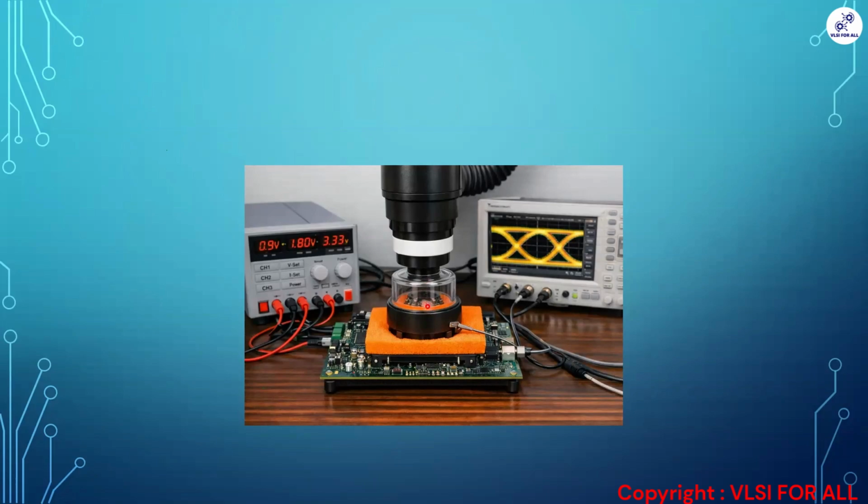To see the SOC behavior, we are sourcing some temperature on the SOC. Like at minus 10 degrees, how does that SOC behave? At minus 40, how will it behave? And at 50 degrees, how does it behave? At 150 degrees, how will it behave? For that, we'll use this Thermostream, in short.